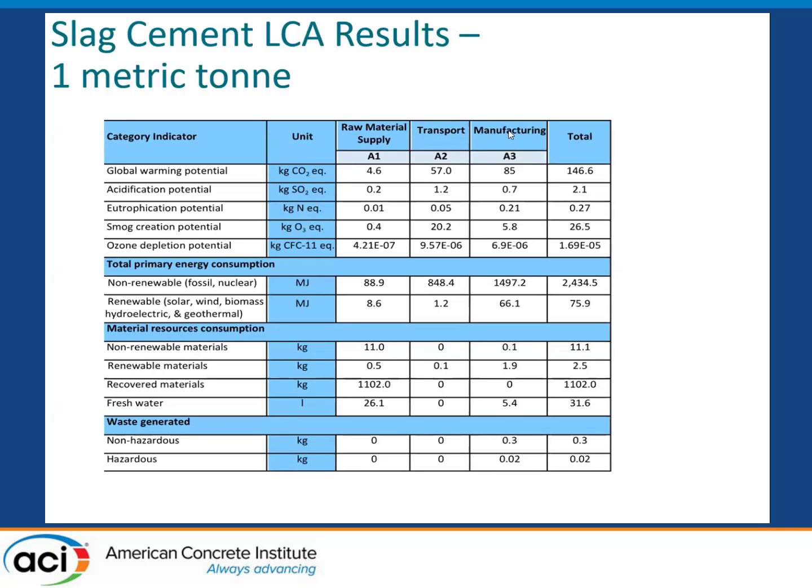So this would also be considered a cradle-to-gate EPD. Ideally, from a building aspect, we're looking at going from cradle to cradle, which means the building gets built, then after the building is being used, you're calculating all of the energy it took to use the building, and then the destruction and recycling of that building. So we're looking at a full cycle, a closed loop, with what we're trying to do.